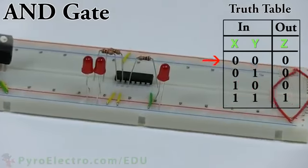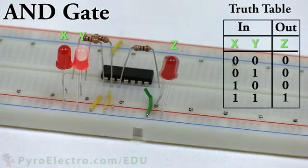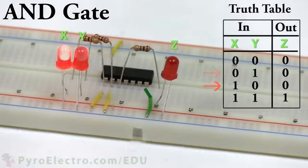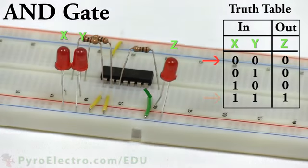Now, using the 2 yellow wires, we'll change input states between logic 0 and logic 1 to verify the truth table. When input is 0, 1, output is 0. When input is 1, 0, output is 0. And when input is 1, 1, output is 1. And that is how the AND logic gate works.